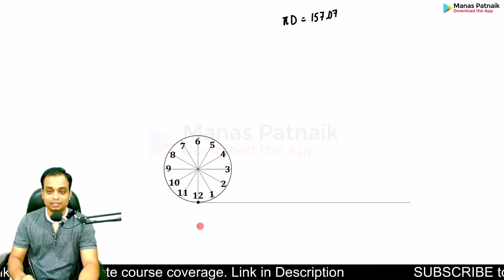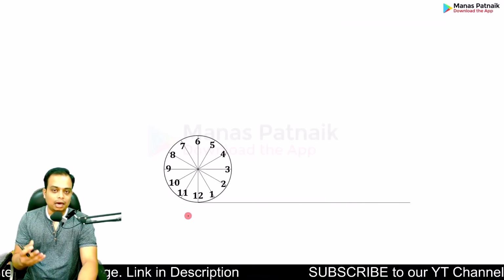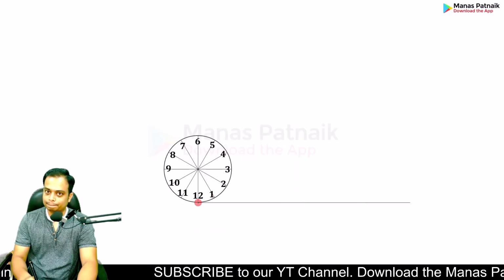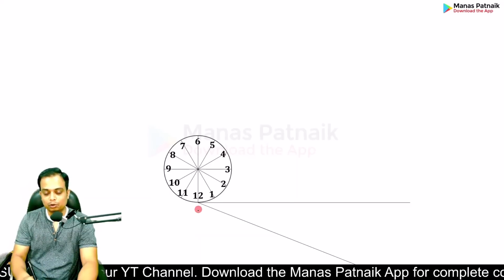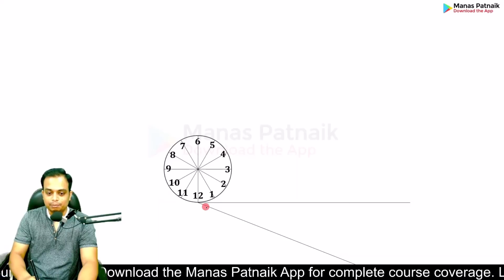All right, so this is 157 basically. Now our objective is to divide this line into 12 equal parts. For that, starting from this very point, I'll randomly make a line at any angle of any random length. And then you need to make points. Keep a scale over here, and at equal intervals of 10 millimeters, keep on marking points.